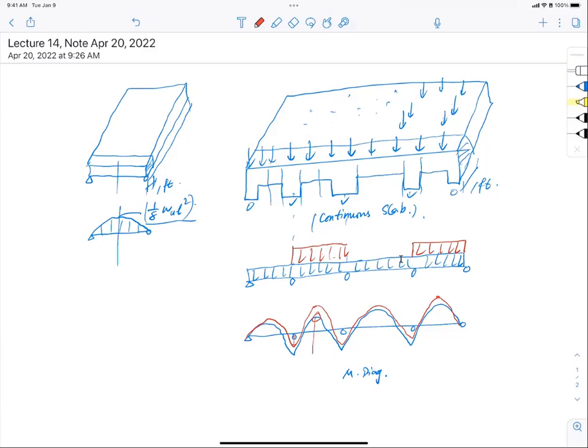That means the location of maximum bending moment, or how much moment at each section, we're talking about either at the support here, which is easy, the zero, but in the positive bending section, negative section, positive section, negative section, and so on, it's not constant. This is a bit confusing, but let me say this: the moment along the span is not constant, and it is changing, depending on the live load pattern or dead load pattern you are placing on the slab.